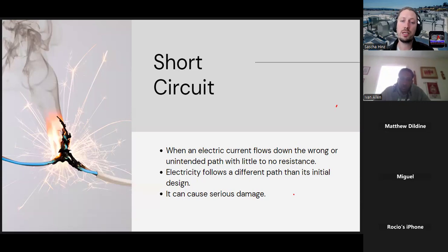A short circuit can be a connection between two wires that does not necessarily trip the breaker. The example that I like to use is, let's say you have a heating coil, your W1 terminal, and your insulation on the white wire is broken. It is making an unintentional connection to your Y1, your yellow wire.